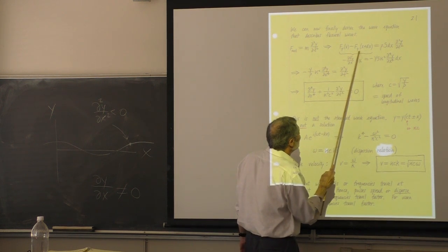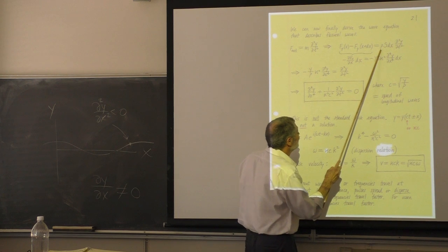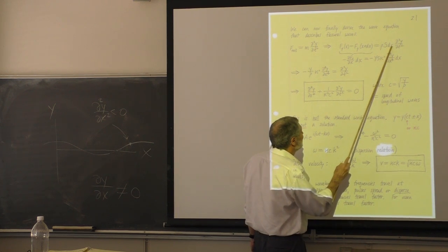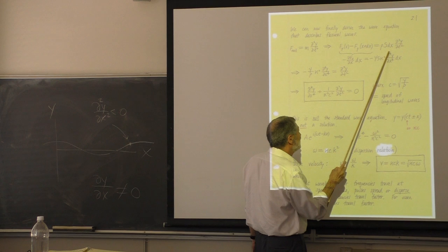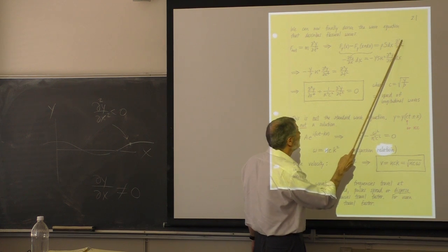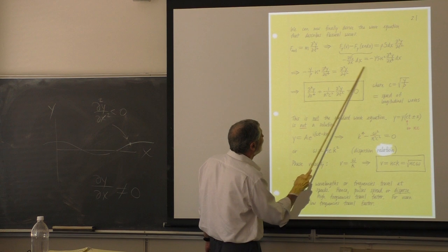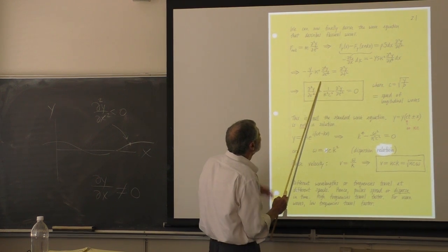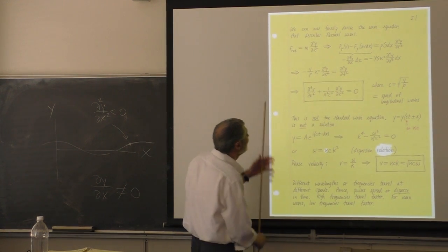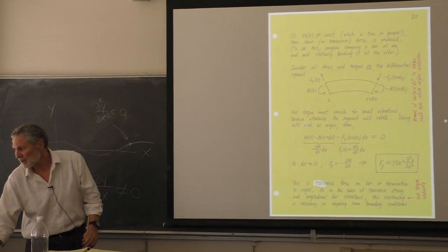This is the force. It must be the mass. The mass is the density times the volume. This is the volume. And times the acceleration, which is 2 time derivatives on y. And now the dx's cancel. And we substitute in what the force is. Here's our expression for the force.